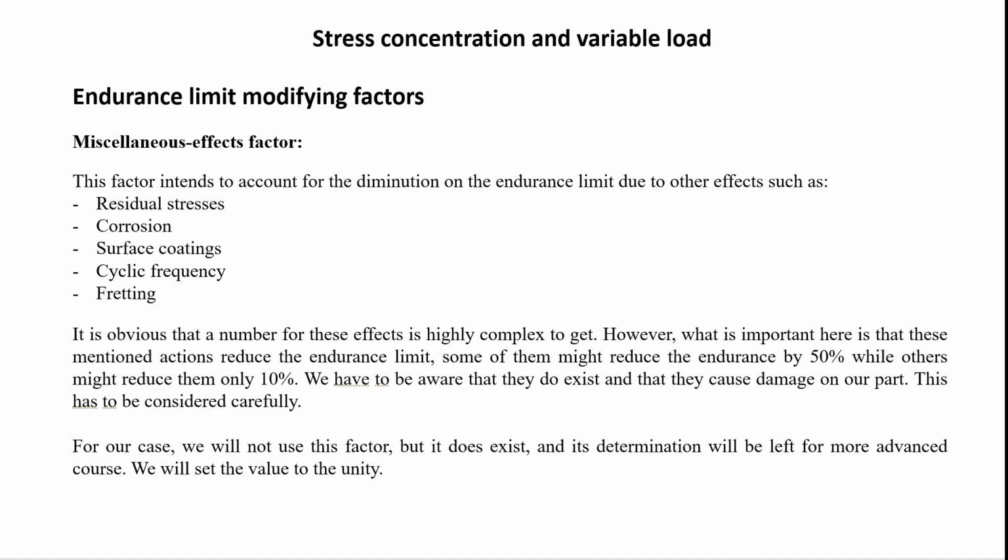And miscellaneous effects are something very complex to determine, as I mentioned. I listed a few of them. For example, when you machine a part, or you forge to create a specific part, or laminate things to create round bars or plates, you are inducing stresses.